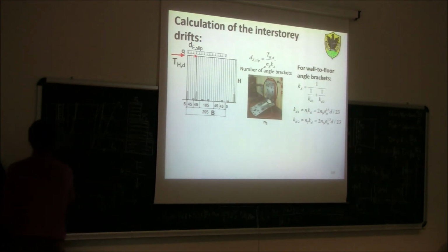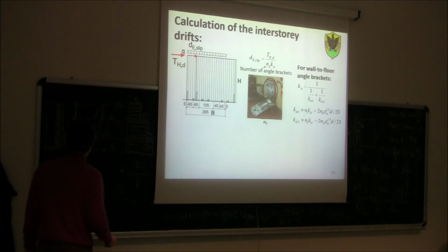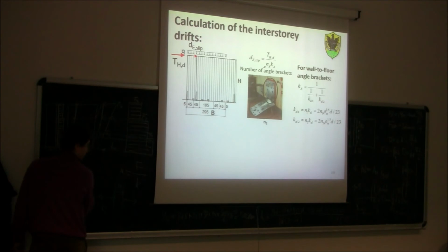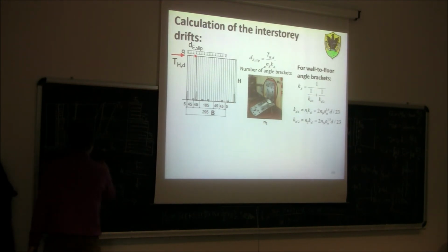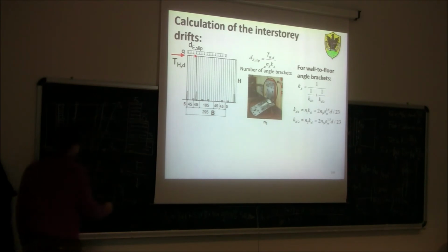But the total deflection can also be written as U equal to U1 plus U2. U1 is the deflection of the first spring, F divided by K1, plus U2, the deflection of the second spring, which is F divided by K2.